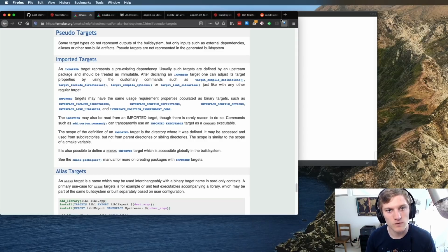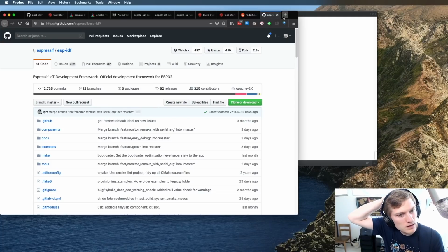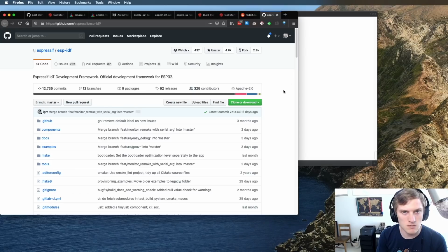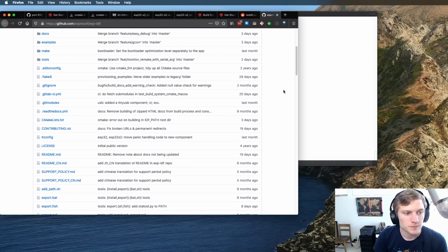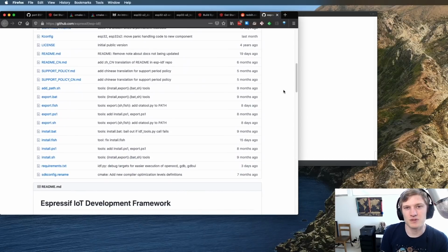But with the ESP32-S2 support, they've switched to CMake from Make, I think. And CMake, in my mind, is having a bit of a renaissance from what I can tell. I was looking at it last night, and people don't like Make. I think one of the reasons is that it's really hard to have separate components of things. For example, TinyUSB is a component that, ideally, if you're using it, you can just say, I depend on TinyUSB, pull those files in, let them worry about what those files are. I'll just say I want TinyUSB. And that's not something Make can really do.